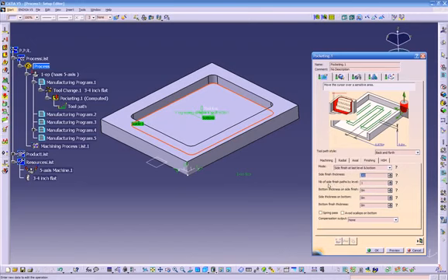Then it's going to ask us number of side finish passes by level. So it's going to ask us how many passes we want. It says 1: bottom thickness and side finish pass. Side, thickness at bottom, everything is common sense. And then if you don't know what it does, you just click on the question mark. See bottom finish. Let's make this 20,000. So right now I just give it a finish on the bottom and a finish on the wall.